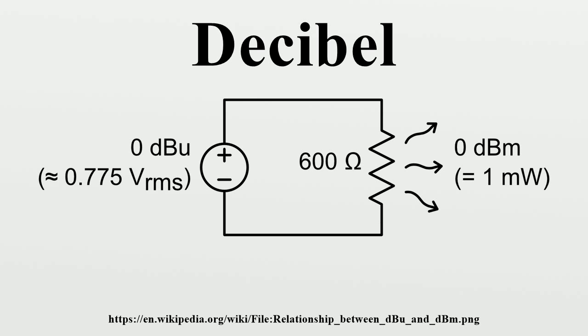In professional audio specifications, a popular unit is the dBu. The dBu is a root mean square measurement of voltage that uses as its reference approximately 0.775 Vrms. Chosen for historical reasons, the reference value is the voltage level which delivers 1 milliwatt of power in a 600 ohm resistor, which used to be the standard reference impedance in telephone circuits.